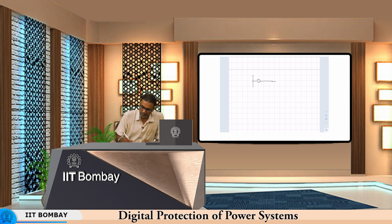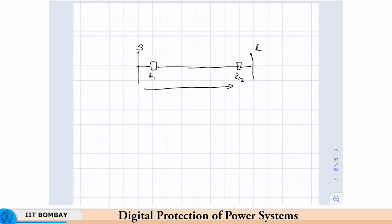So, assume that this is the line that we are seeing between sending end and receiving end, and the relay here is say R1 and the relay here is R2. This relay covers about 75 to 80% of the line, sometimes 85, in its zone 1. The other overlapping zones, etc., and the extension of zone 2 to cover 50% of the next line or 20% as the case may be, and the extension of zone 3 to cover 200% of the next longest line. All that we have seen in the previous lecture.